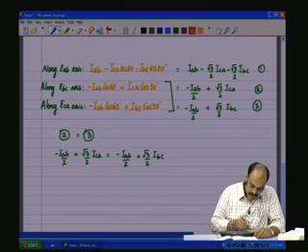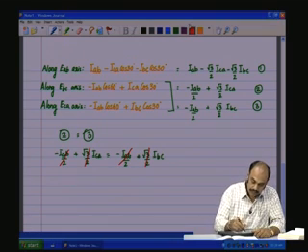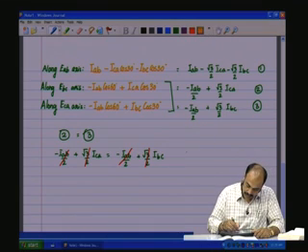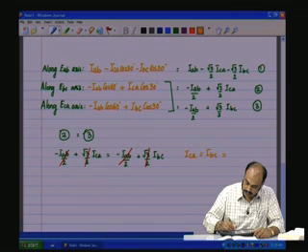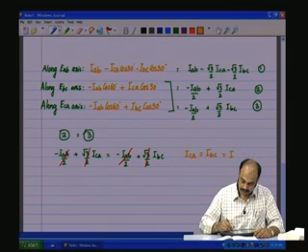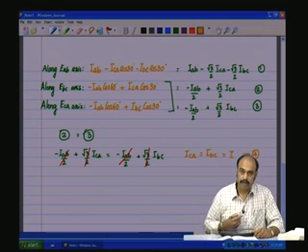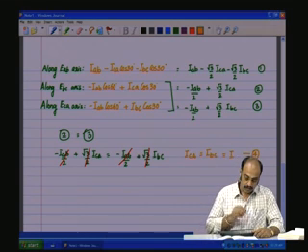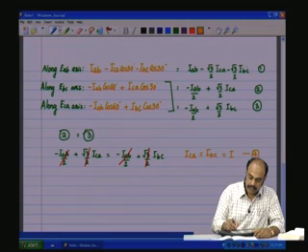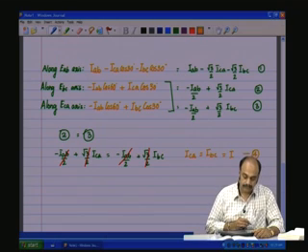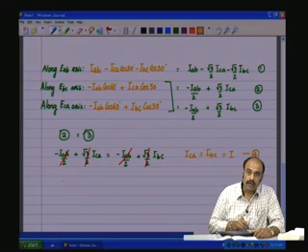So, here we remove this, so we have a result which is I_CA should be equal to I_BC, and we will say that is equal to some value I. This is number 4. Now, let us substitute I for I_BC and I_CA in 1 and then solve for I_AB.